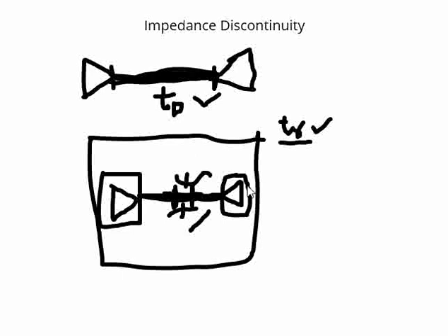Let us assume the length of the small patch is L. If the length of the small patch is much lesser than the transmission line signal rise time, then this can be done. This can be blindly implemented in the PCB design. So for that short patch, you can definitely have impedance discontinuity and still see a proper signal at the receiver with much lesser reflections on the channel.